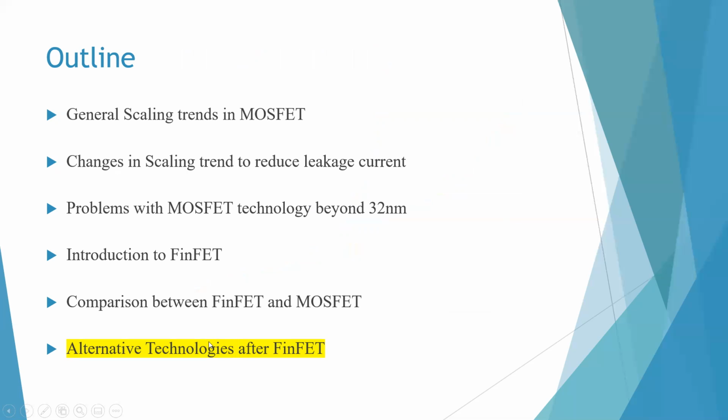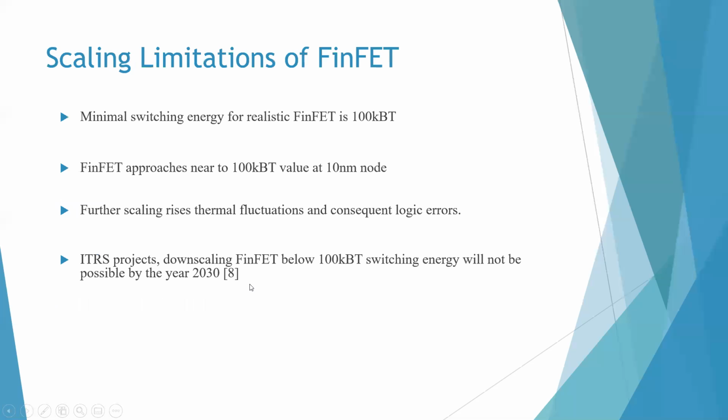So basically, there are limitations to scaling FinFETs further. The minimal switching energy for a realistic FinFET is 100 kBT, and FinFETs are already approaching that value at the 10 nanometer node. Further decreasing FinFET dimensions might result in increased thermal fluctuations and consequent logic errors.